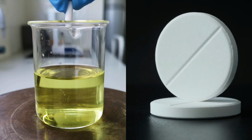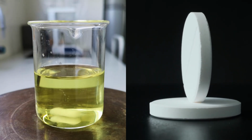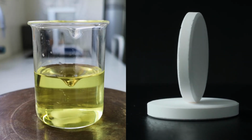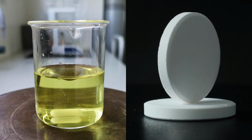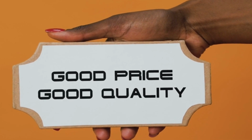Due to safety concerns with handling chlorine gas, many small water systems will choose to use liquid chlorine or one of the various dry calcium hypochlorite products. Chlorine is affordable and effective, but it can react with organic matter in water to form disinfection byproducts, which are regulated by law. Chlorine can also cause taste and odor complaints if not used properly.